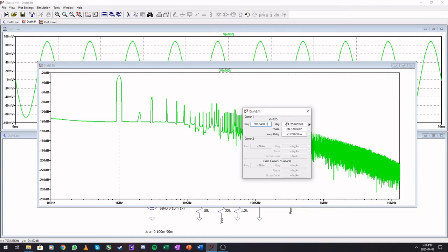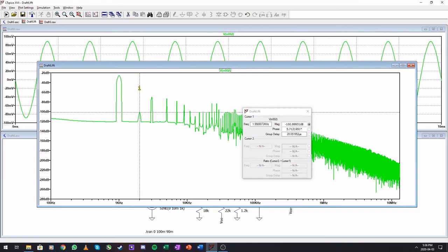Right, so we can see that this is sitting at minus 24 decibels. We can move this to this point. That's 2 kilohertz. That is, we should see a second harmonic popping up there when it's not linear. And there is going to be other frequency components, but this is mostly noise.